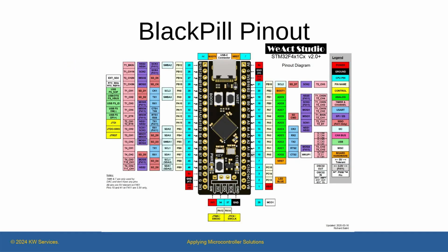On the black pill pinout diagram, the I2C pins are mostly on the left side and are the color light blue. The black pill has 3 I2C ports available. Since we need some pins for other functions, we will only use the I2C1 port at PB6 and PB7. Fortunately, an I2C port can communicate to multiple devices.